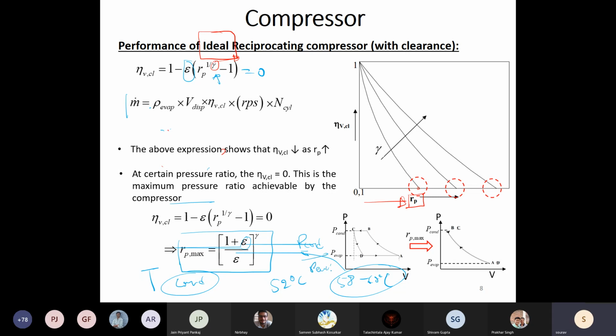by the evaporator pressure. The worst evaporator pressure would be corresponding to 16 degree. So your ACs will go as low as 16 degree if you try to set it by the remote. So that would be the maximum or worst scenario for the compressor. It will just deliver some mass flow rate at this condition.